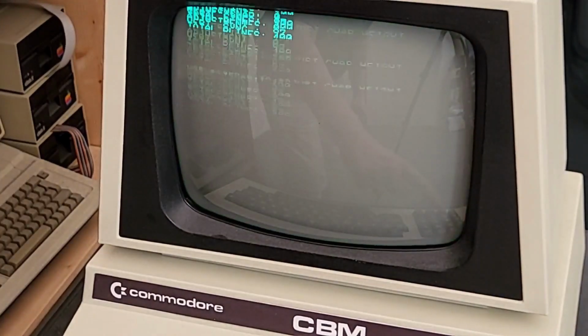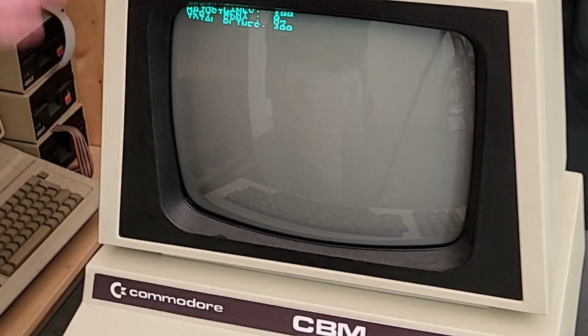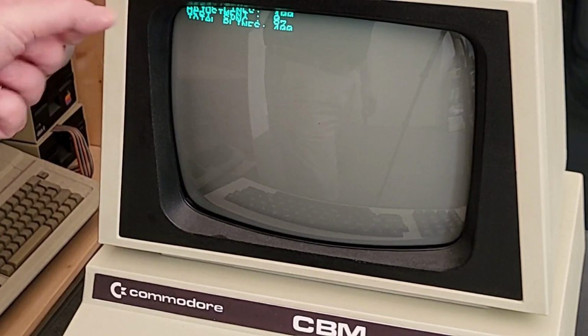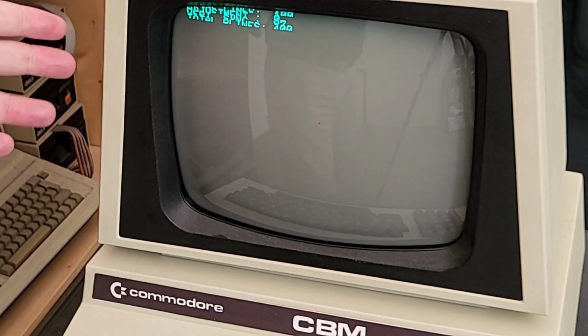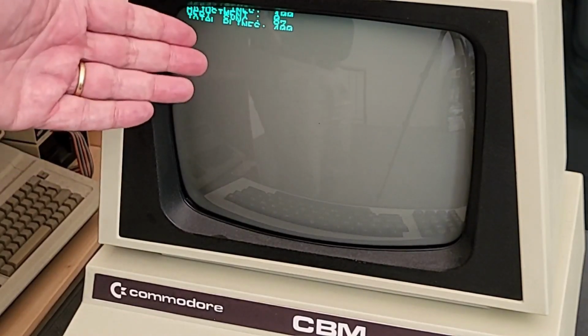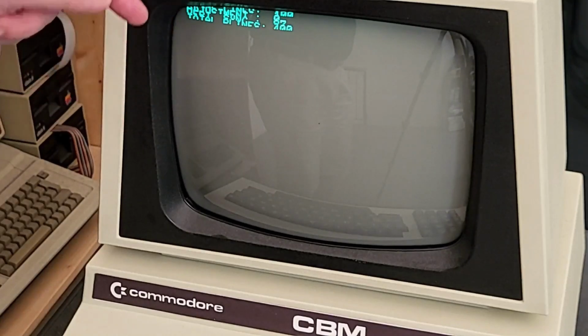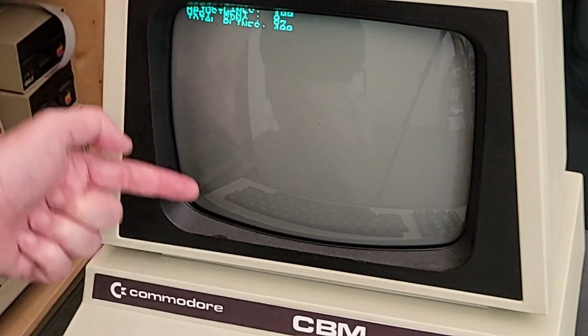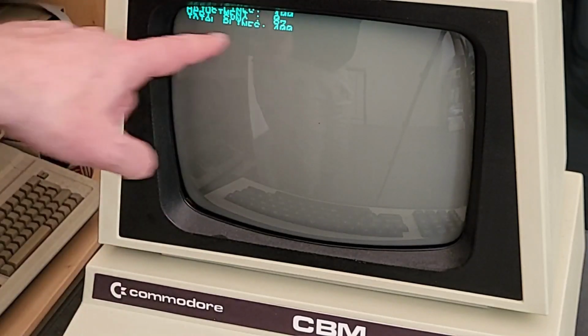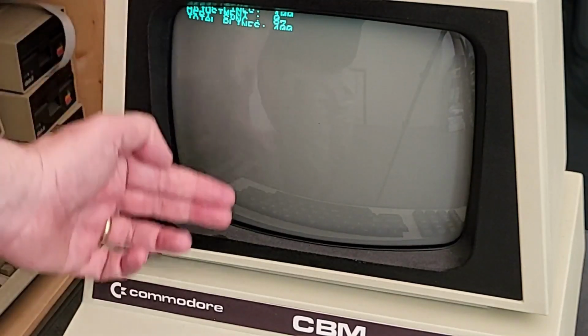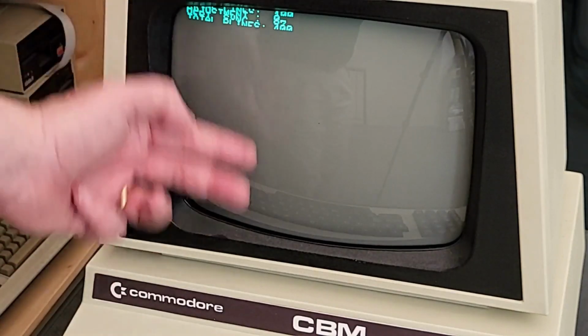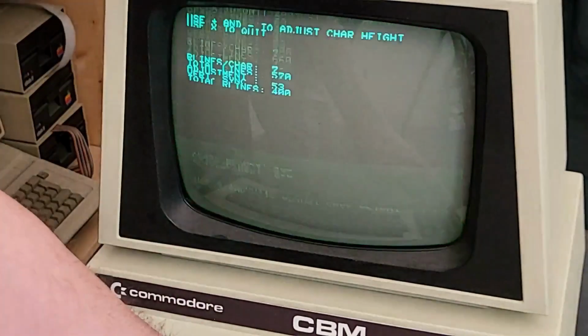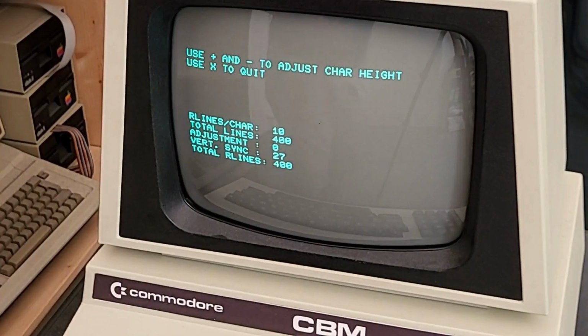Okay, 5 and 4. And then 4 is basically the minimum you can do with static timing, because if you go below 4, you would need to have more than 128 character lines to display the whole screen with 400 total raster lines, as is required by the screen geometry. But we can work around that as well.